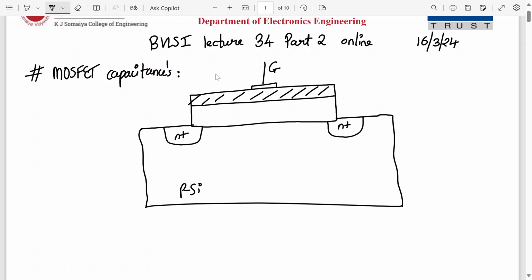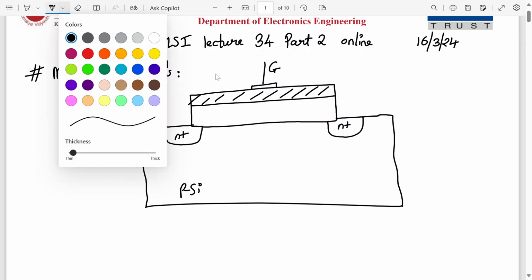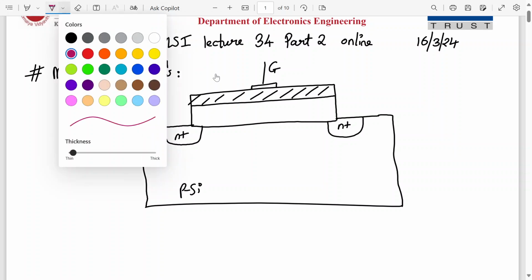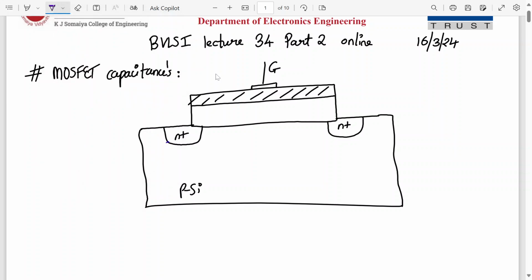Okay, now as informed earlier, these are junction capacitances, so these are related to the PN junction. There are two more layers present. This is P plus, which is actually the channel stop implant. This is source, this is body, and this is your drain terminal. This P plus region is a channel stop implant to prevent the formation of any illegal channel between adjacent MOSFETs on the same substrate.